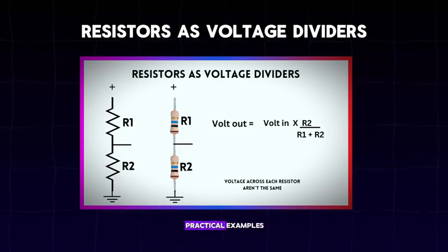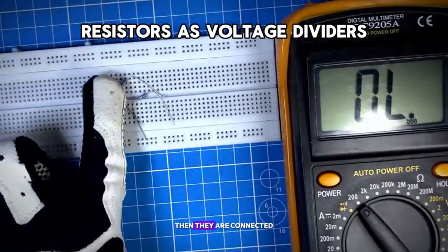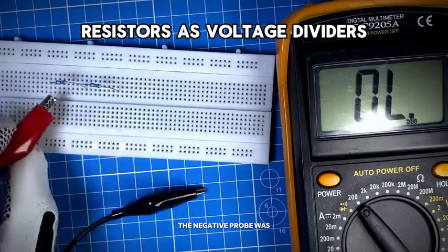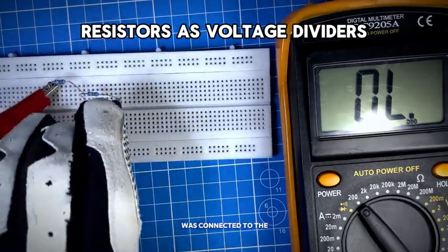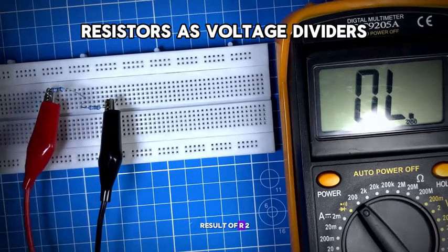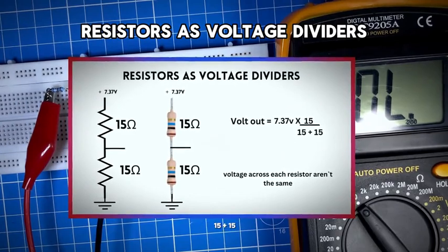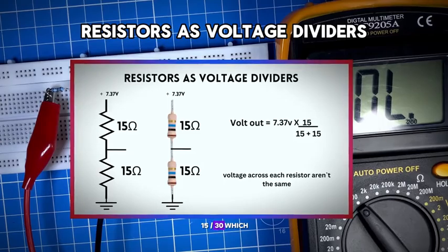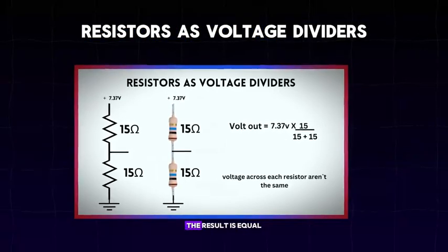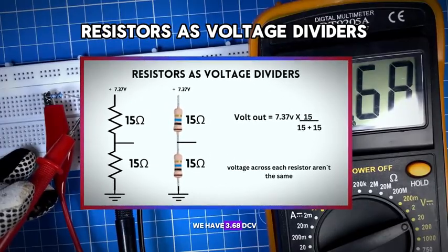So let's use some practical examples to see how voltage dividers work. These resistors are 15 ohms each. They are connected in series, and 7.37 volts DC was connected. The negative probe was connected to one end, and the positive probe was connected to the other end. To find Vout, multiply 7.37 by the result of R2 divided by R1 plus R2, which is 15 divided by 15 plus 15. So 15 divided by 30 is 0.5. Then 7.37 multiplied by 0.5 is equal to 3.68 VDC. As you can see on the multimeter, we have 3.68 DC volts.